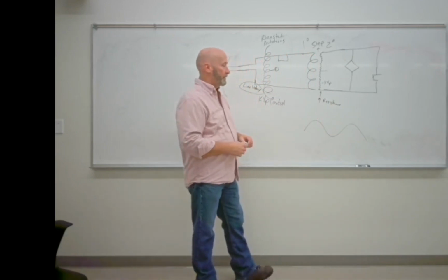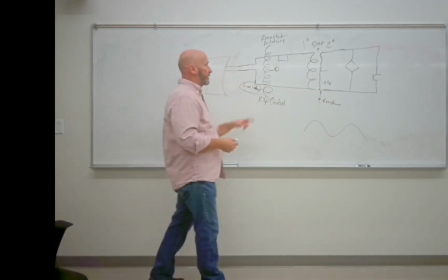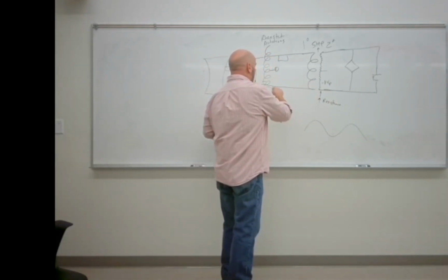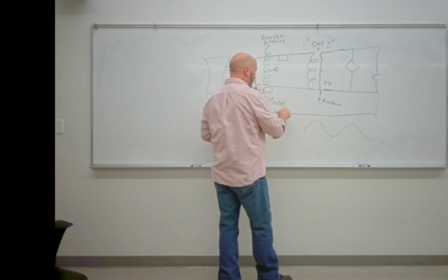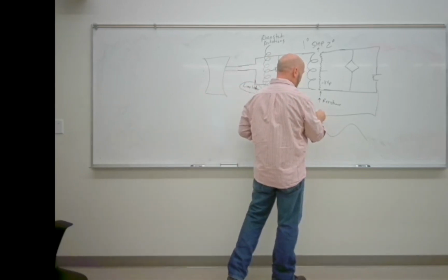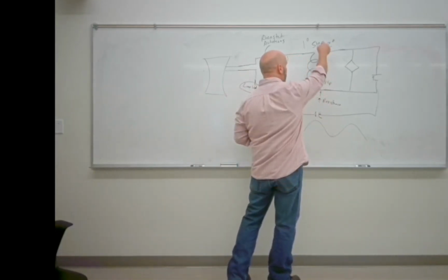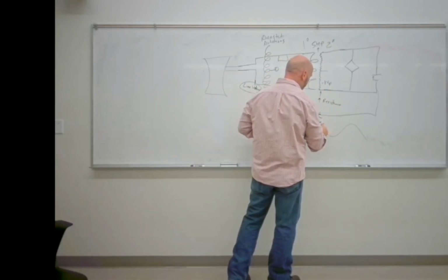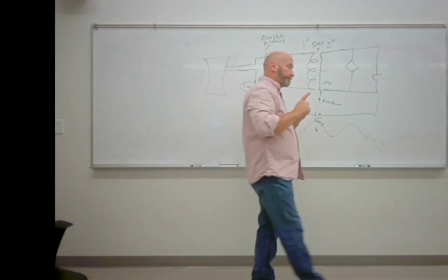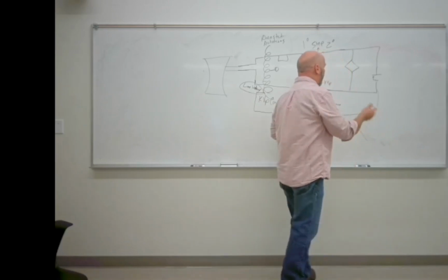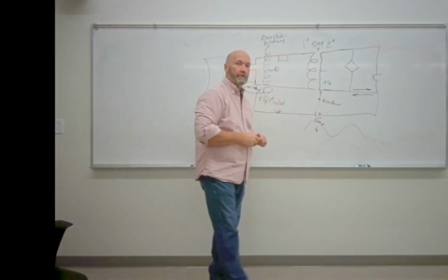What you get out of the wall is alternating current. So it goes in and out and in and out and in and out. We have to have alternating current to make these things work. We've also got a secondary circuit that comes off, and that's how we control our milliamperage. Remember that, talking about that? Milliamperage, we have exactly the opposite type of transformer. If that's a step up, this is a step down transformer, right? Now, the reason I'm pointing all this out is because if we have alternating current, that means the current's trying to go in that direction, and then it's trying to reverse direction and go opposite direction.